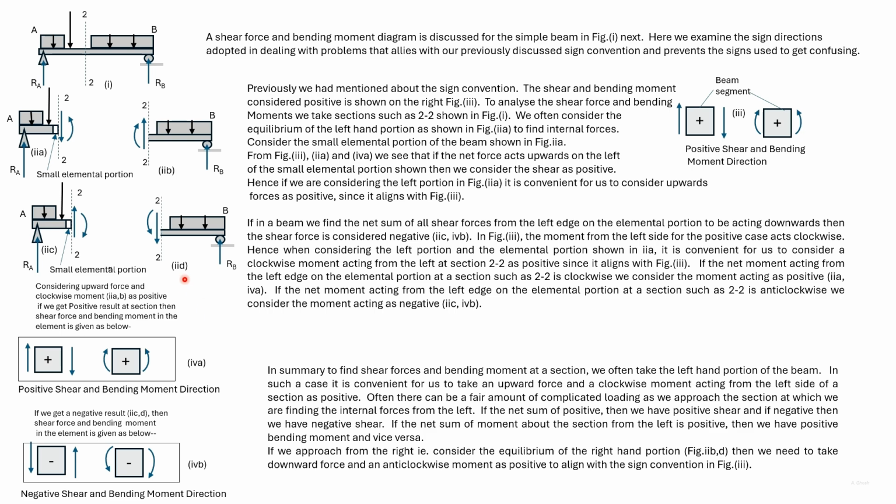If we consider from the right side, then unlike what we have ascertained from the left side, a downward force is considered as positive since it matches with this sign convention. Also, an anti-clockwise moment needs to be taken as positive to match with our sign convention.